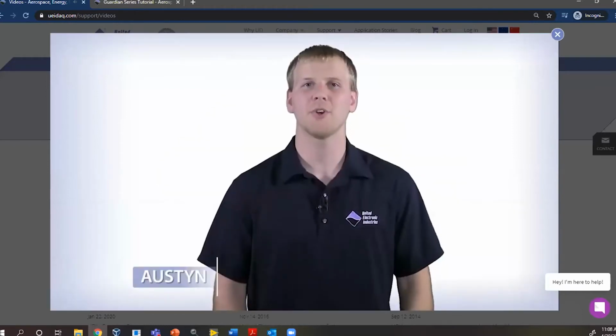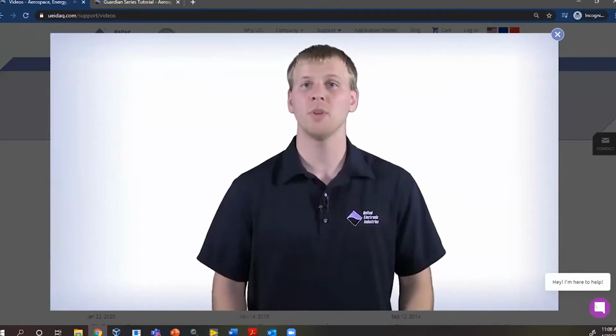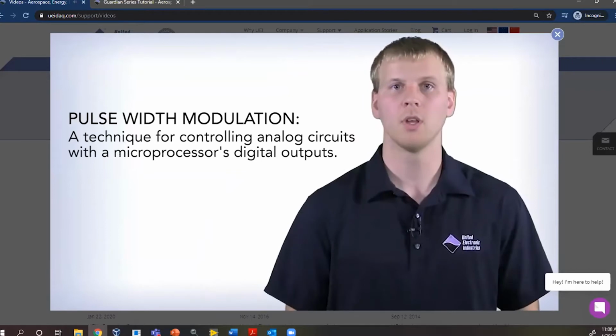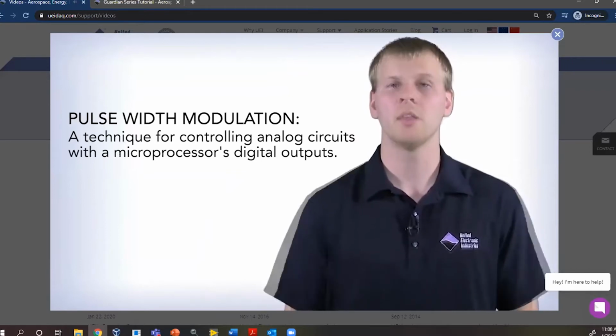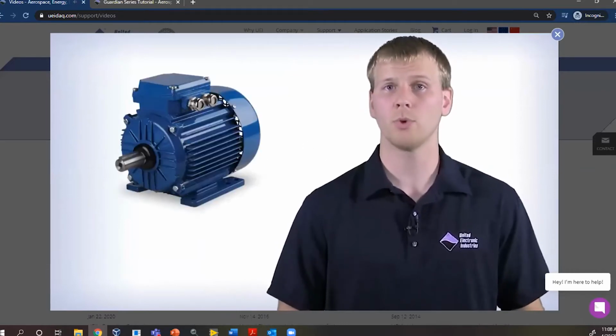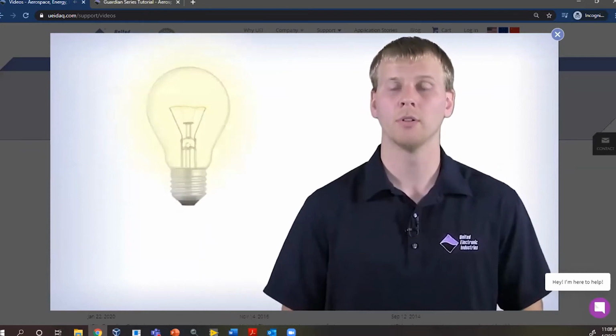Hi, my name is Austyn Turner, and I'm an application engineer here at United Electronic Industries. Today I want to talk to you about UEI's implementation of pulse width modulation. Pulse width modulation, or PWM for short, is a technique used to pulse a signal at varying widths. This is used in a variety of applications, such as motor control, power delivery, light control, and more.